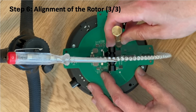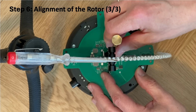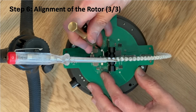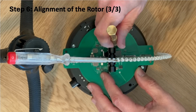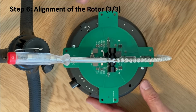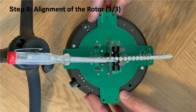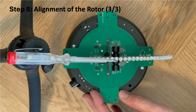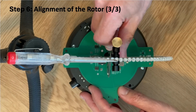To do so, you first loosen the corresponding mounting screw and then fine-tune the position using the adjustment screws. As you can see, it now looks a little bit better, but you need to repeat this process until the LED board is properly aligned.